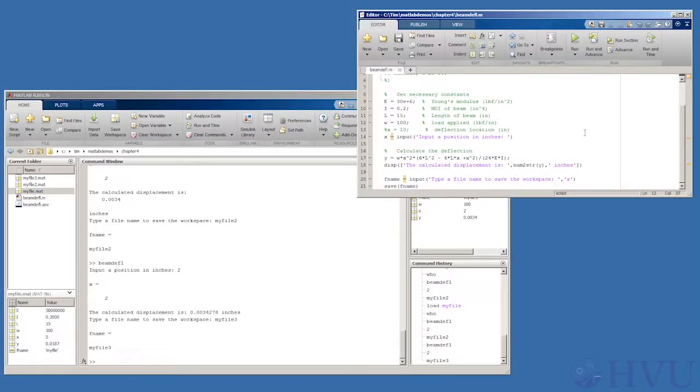Suppose I want to display all of the values used by my beam deflection program after the code runs. Using MATLAB's default display, or the disp command, will get sort of awkward, since a lot of material will scroll past with more white space than is really necessary. In this example, I'll show how the fprintf command might be used to improve things.